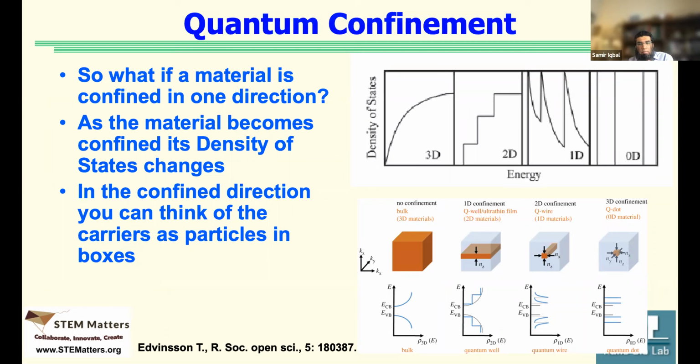Now, there's very involved physics, but there are simple approximations that are done in common solid state device expressions, where we then take care of band gap problem, absorption coefficients, and density of states in what we call low dimensional materials. So there is a thing called the time-dependent Schrodinger equation, which basically takes care of the interaction between light and electron.